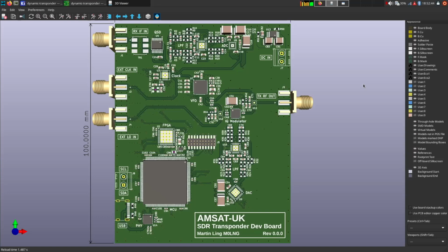So 24-bit ADCs, fully differential paths, over 100 dBs of dynamic range, which is not something we're going to have the ability to make full use of with the kind of compute resources that we can put in the power budget of a 2U CubeSat. But you can also take this and just use it as a baseband, and pull out all of that data over USB through the microcontroller to crunch it on a big powerful PC or whatever, to see what's possible if we did have the resources, right?